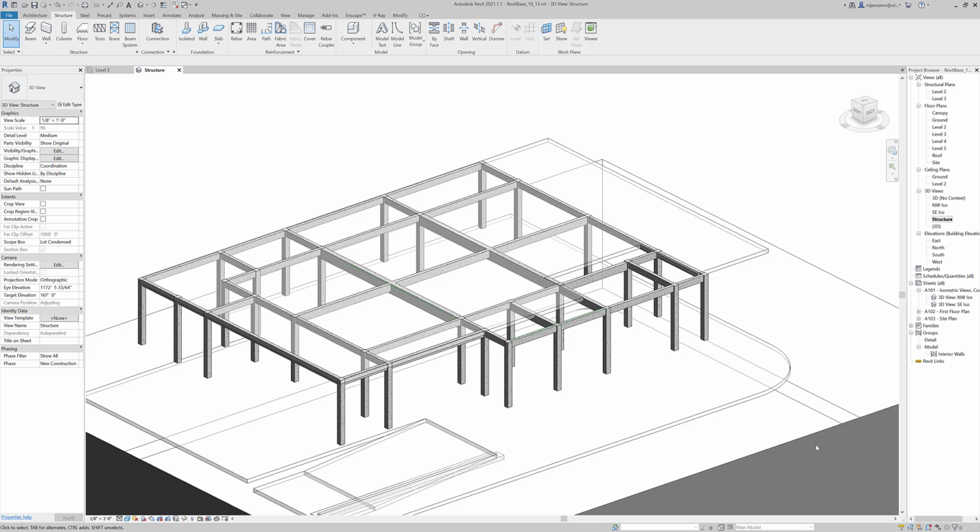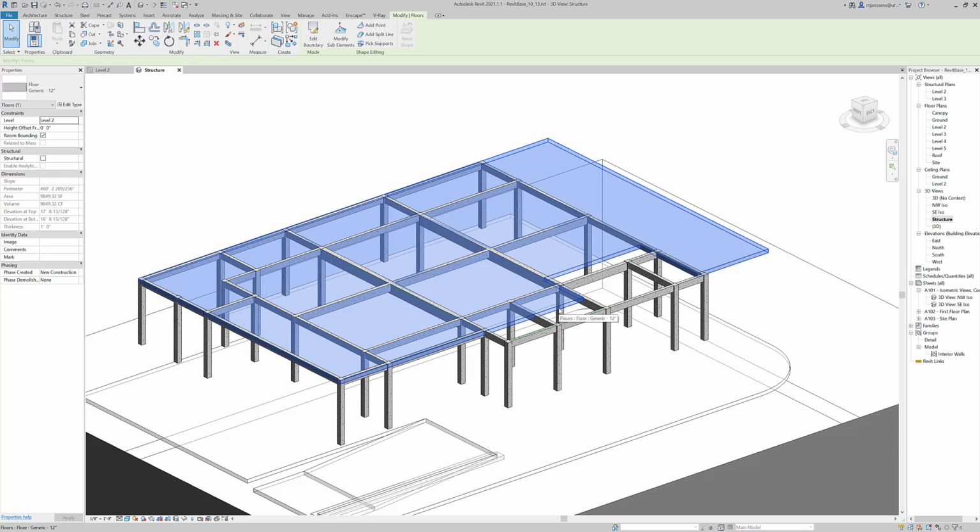So the last thing we have to do for our concrete structural system is change the slab. Now the way I showed in the previous floors tutorial is sort of a generic 12-inch floor that can account for a number of different things, and it's just sort of a massing floor. We want to do a couple things. We want to change the profile of this, or the boundary, so that it ends at our concrete system, and then we want to change the material and the structural depth of it.